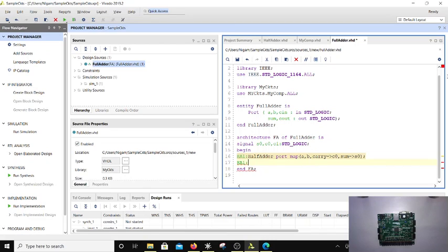The second one is going to be a simpler one, which I will do just by sequence. I'll say half adder, the name of this, and then port map. Here A in this case is S0, comma B in this case is C in, comma sum is the same as sum, it's the output pin, and then you have C1. Then close the bracket and add a semicolon. Since this is red, I have to rename it, so this will be called HA2. You cannot repeat the name. Now there is no red line, which means the second instantiation is also correct.